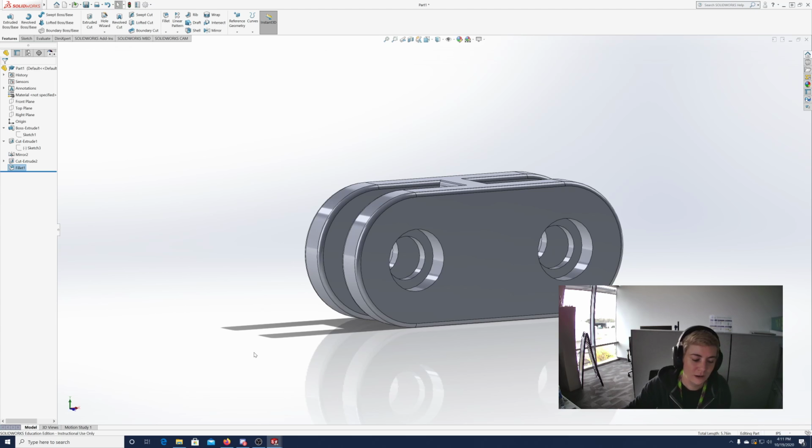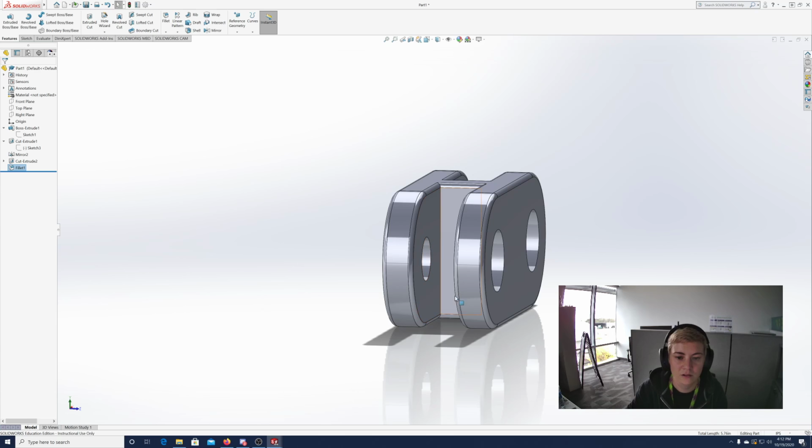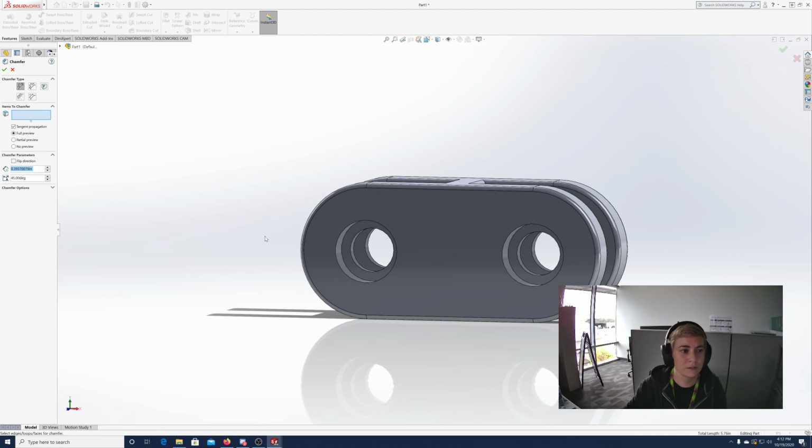And then we're going to add chamfers to our holes here. It looks like they want chamfers on the outer edge of the counterbore and then also on that inner edge. I don't believe we're doing anything to the inside holes here, so those are just going to stay the shape that they are. But we're going to chamfer these edges. That's also under the fillet tool. If you click the little down arrow, you'll see chamfer underneath.